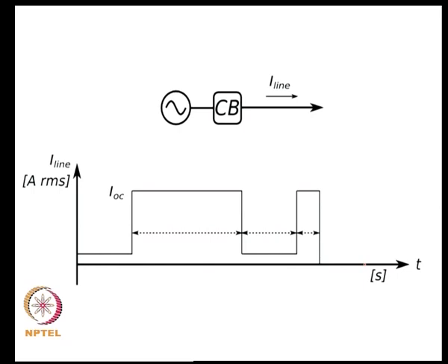So, if you look at an example of, say, a circuit breaker where we will assume that its reset time is of the order of, say, 5 seconds, and it has an overcurrent level IOC, and at that particular value of IOC, with your parameters of the breaker, suppose you had a trip time of, say, 2 seconds.